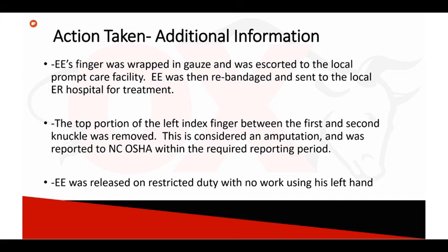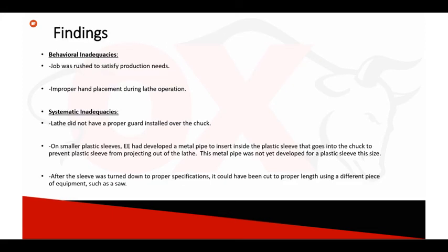Page 9. Findings. Behavioral inadequacies. The job was rushed to satisfy production needs. Improper hand placement during lathe operation. Systematic inadequacies. The lathe did not have a proper guard installed over the chuck.